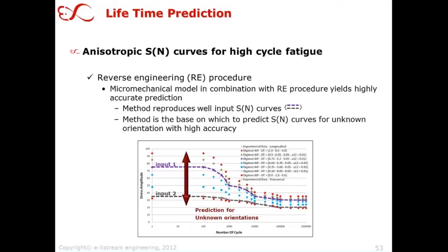And you apply this model by reverse engineering to the input SN curves that I mentioned. So basically, again, you would injection mold a plate with aligned fibers. Then you cut out at different angles, and for each different angle, you have an SN curve. And then you reverse engineer the failure behavior as given by the model on the previous slide to your SN curve.